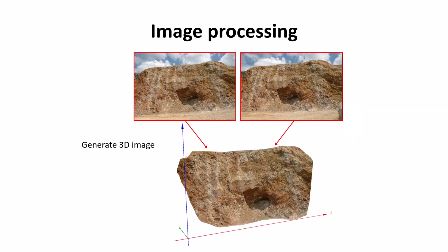And those images are now brought into the software, and if you have ground control or scale bars, that information is brought into the software, and that you'll experience later. And you end up building a 3D point cloud and a 3D digital terrain model, kind of as illustrated here.